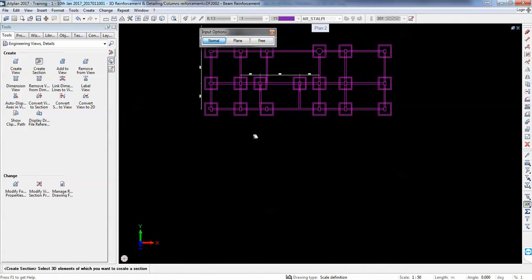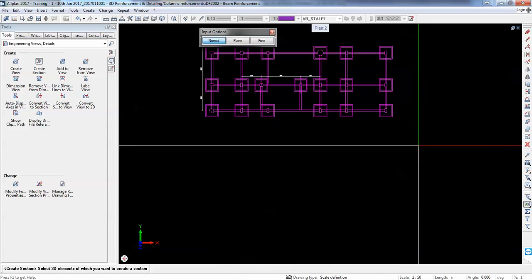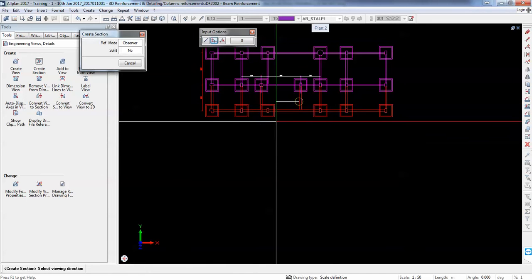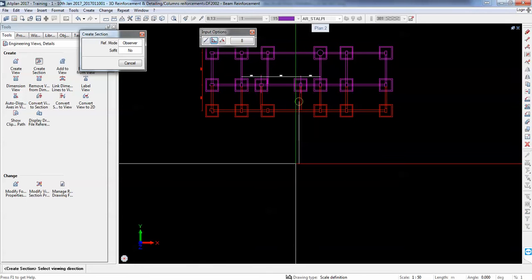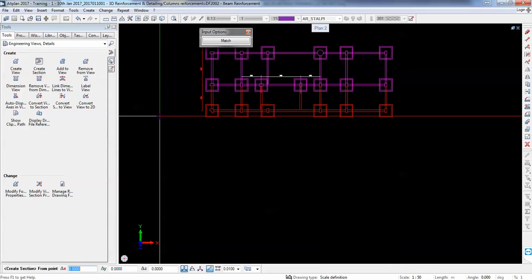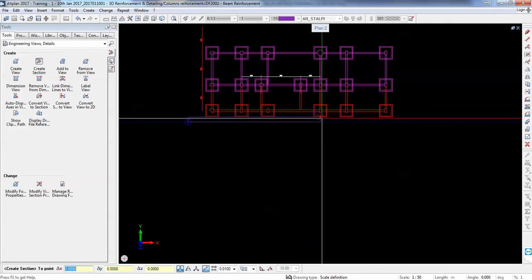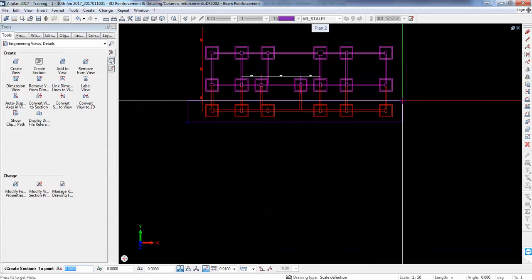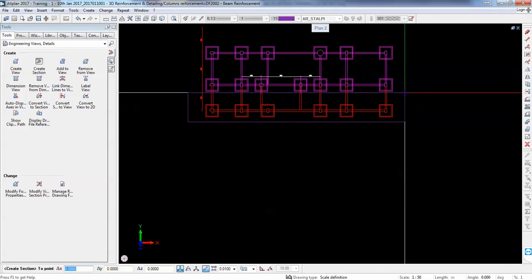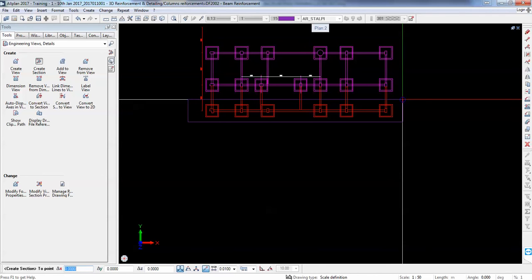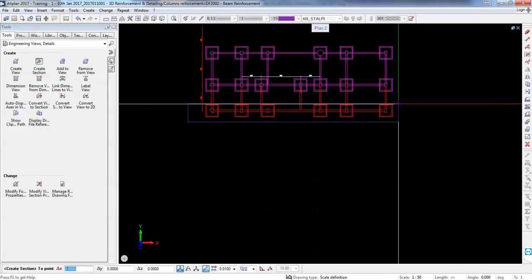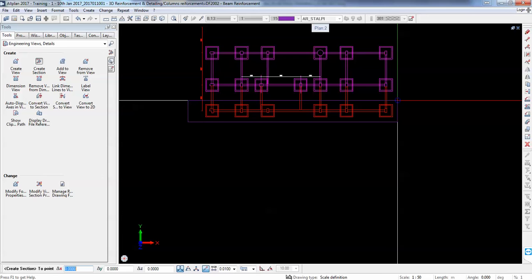So how I do it is the following. I just say create section. I select the objects. I select the area where I look from, so the direction towards the circle. I just make one click here, one click diagonally, and this is basically a shortcut for doing a small rectangle. If I do another polygon, we'll get a cross section in that polygon.